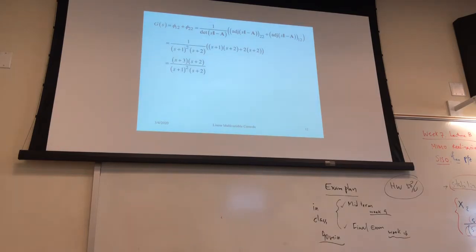Then you have something called a zero-pole cancellation. But both of them are stable, in the left half plane, so -2 is in the left half plane. So this cancellation will not cause an internal stability problem. So that is a second order system. Remember, the A matrix is 3 by 3. Therefore, since this is lower than 3, the original system realization is not minimum. It's not minimum.